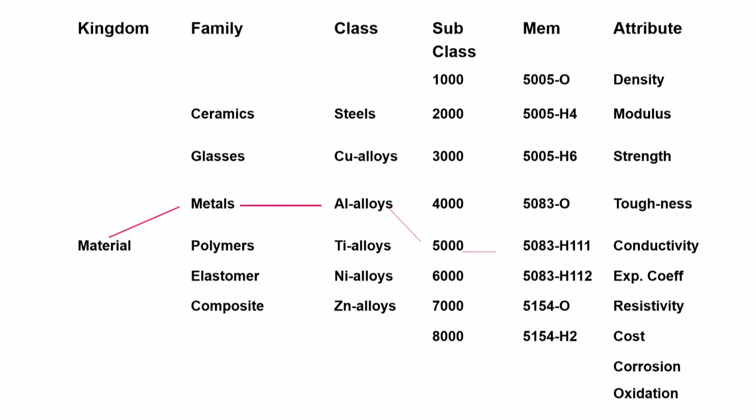Well, first of all, I choose a material because it is a product. Then which family do I have to choose? Ceramics, glasses, metals, polymers, elastomers, composites. Property limits we are going to apply, and then we will naturally see that the strength requirement and all these things will keep the metals and the composites as two candidates, but composites till today, other than the aircrafts, application of composite for automobile is very expensive.